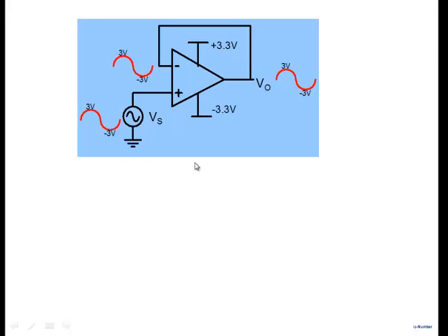Let me show you a differential pair. All of you know it is a part of an op-amp. So look at this case also. If you look at this case, a buffer, and suppose I apply a 3 volt sinusoid. So this is a 3 volt sinusoid, and you come back here. This also obviously is a 3 volt sinusoid. So note that the input common mode voltage is 3 volts.